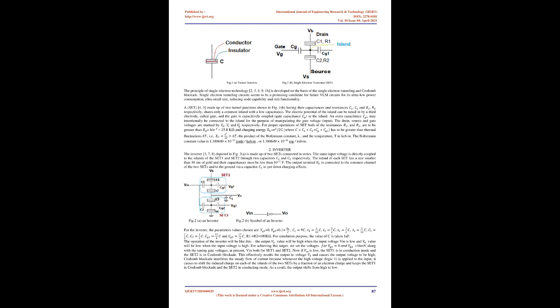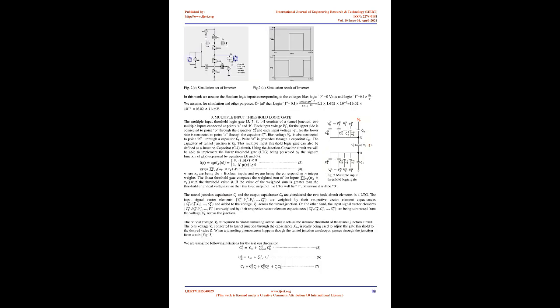If two conductors are connected with an insulating layer between them, there will be not only a resistance but also a capacitance in the junction. In this context, the insulator acts as a dielectric, and the two conducting plates with the dielectric form a capacitor in the tunnel junction. For the discrete nature of electric charge, current flowing through a tunnel junction is a series of events in which merely one electron will be able to pass or tunnel through the tunnel junction.